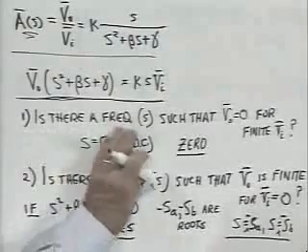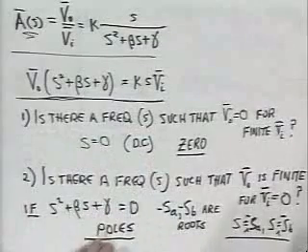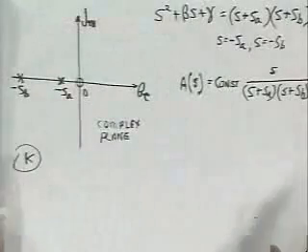Say that again. If you have a pole zero diagram for a circuit or any linear system, that diagram locating the poles and zeros contains all the information about the dynamic behavior of that circuit or system, except for some scale factor. Not that it's unimportant, but all the dynamics is contained in the portion of the expression that depends on S, the complex frequency. So, to review, we've found roots of the numerator, which we call zeros, roots of the denominator, which we call poles, and plotted them on a complex plane.